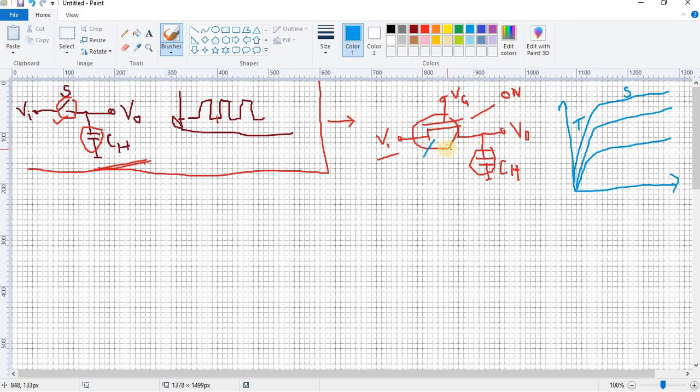So under these conditions, let's first write the equation for the resistance for this particular MOS structure, considering all the parameters, say mu n, Cox, W by L for the structure and all those things. So the relation for resistance can be written as mu n Cox, right, W by L into what should be there, VGS minus VT.